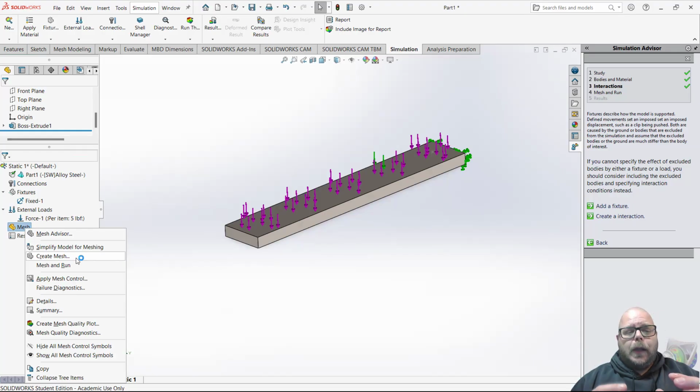But it gets a lot more mathematically complicated. So what we need to do is create a mesh. What the mesh will do is take our geometry and facet it, sort of like it would if we transformed this thing into an STL file to print. It's going to create a mesh with a bunch of triangles, and it's going to treat every edge of those triangles like a two-dimensional stress problem. And we could do that mathematically.